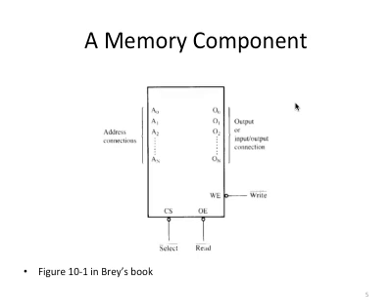WE is write enable. If this chip is writable, then you have this write enable as a control pin, basically to tell the chip whether or when you need to perform a write operation. For memory chips that are read-only, you don't need write enable because you don't perform write operations. Also, the write enable is often active low, so you need a logic 0 to perform the write operation.